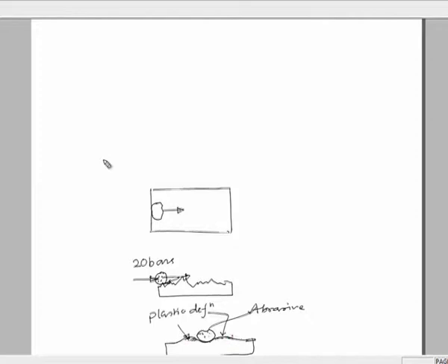On subsequent progression of these abrasive particles through this workpiece surface, work hardening occurs on these lips, and subsequently these lips are removed in the form of microchips.